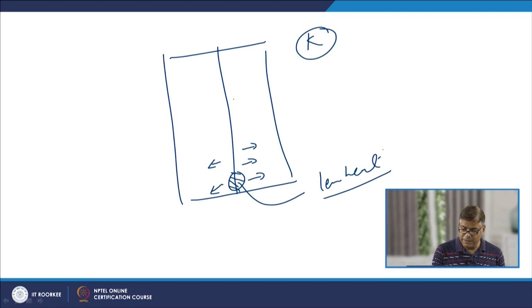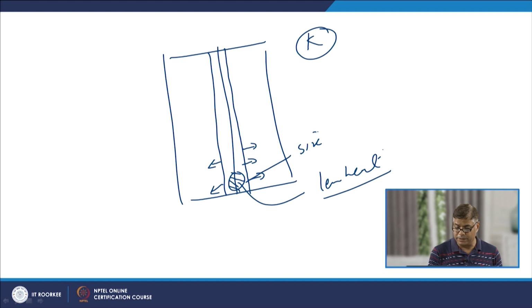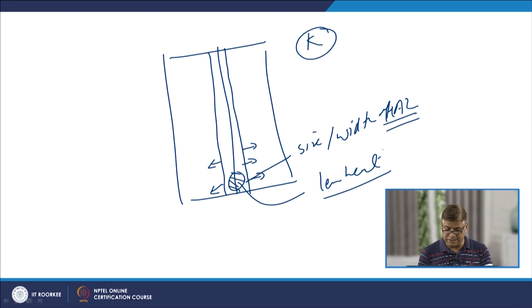At the same time, since less heat dissipation to the base metal takes place, the size of the heat affected zone, measured in terms of the width of the HAZ, is very limited in the case of stainless steel. So, less heat input, less power is needed for welding stainless steel as compared to the carbon steels, and the width of the heat affected zone is smaller.